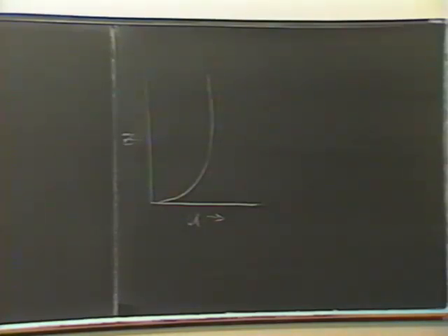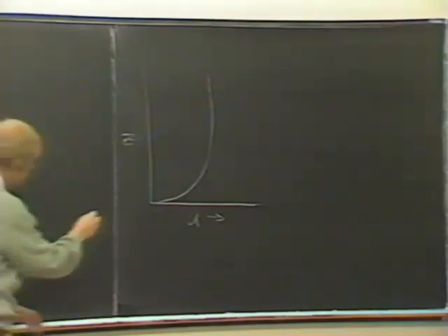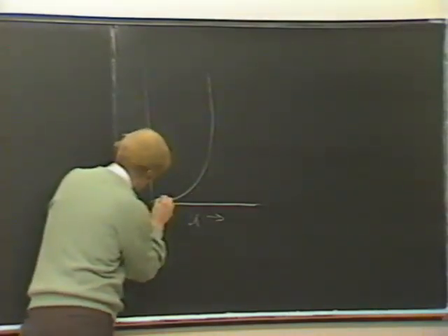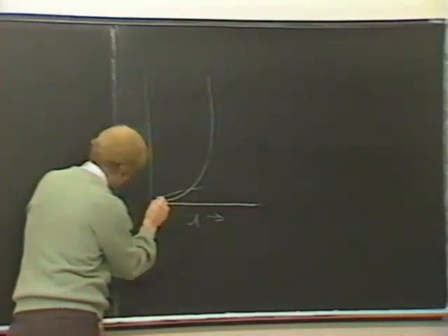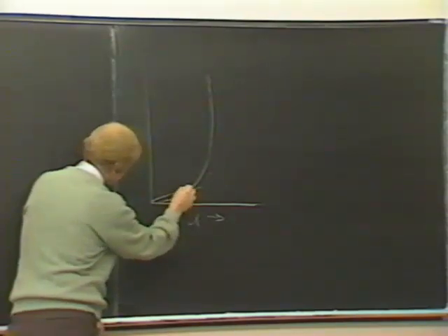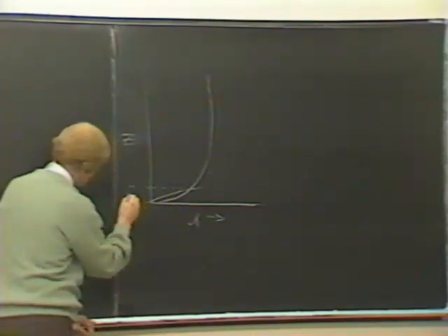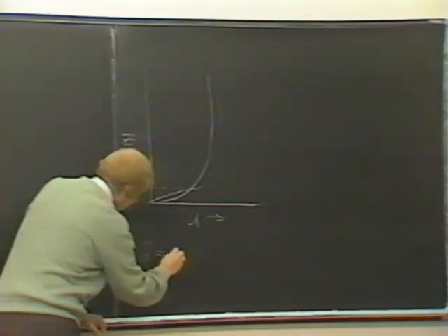Or if you remember, the plane's going through air that was reasonably still compared to the velocity of the airplane as it moved along, so that somewhere just outside of that it's shedding eddy. This formation of a viscous layer, and we'll say that the average time of the... I'll draw an enlarged view of it. The average velocity gradient in the viscous layer looks something like this. And we call this thickness here delta, and delta is equal to 11.6 nu over u star.